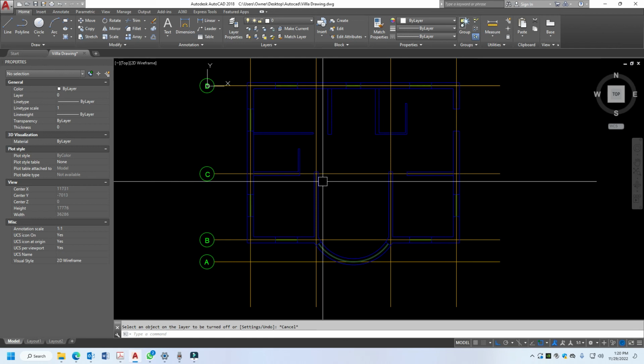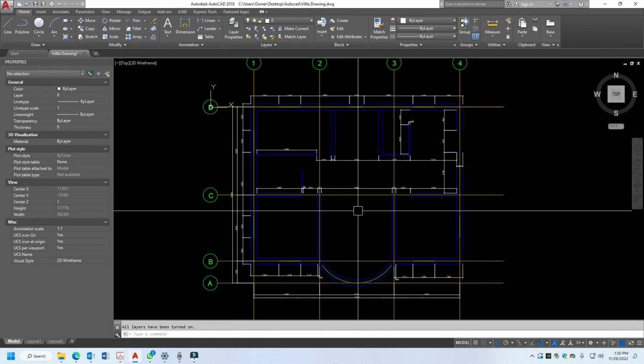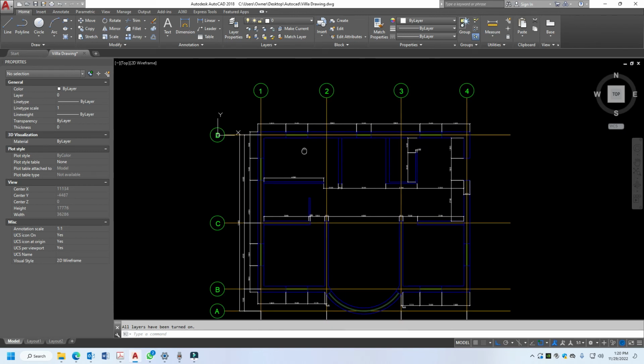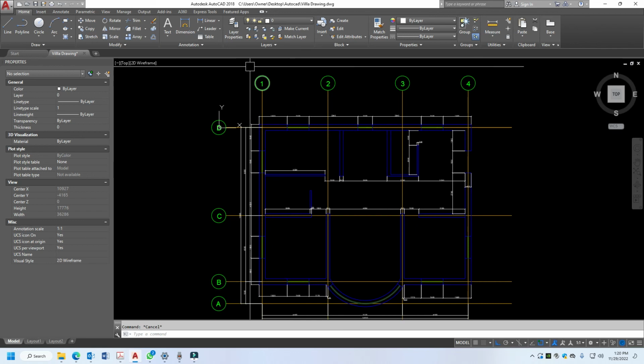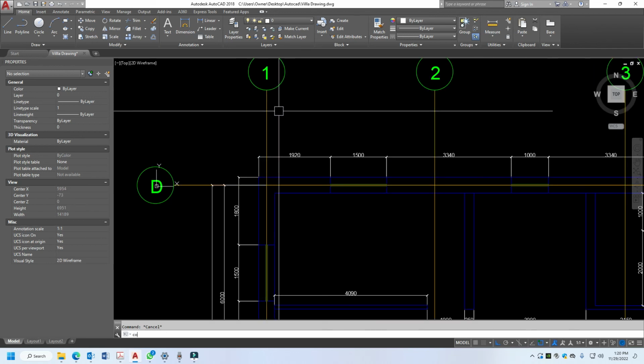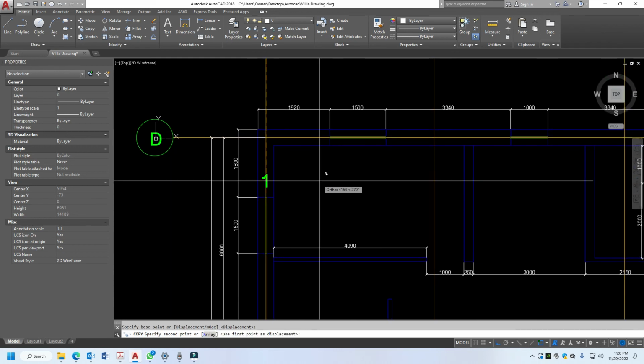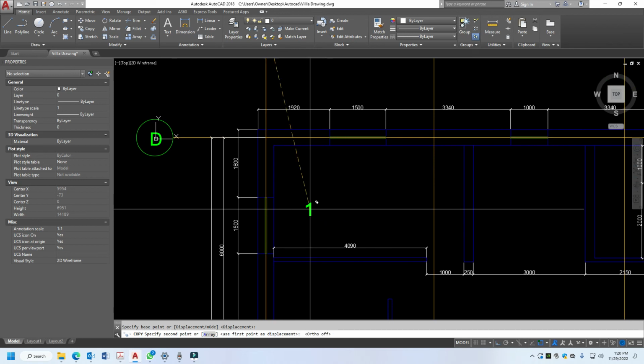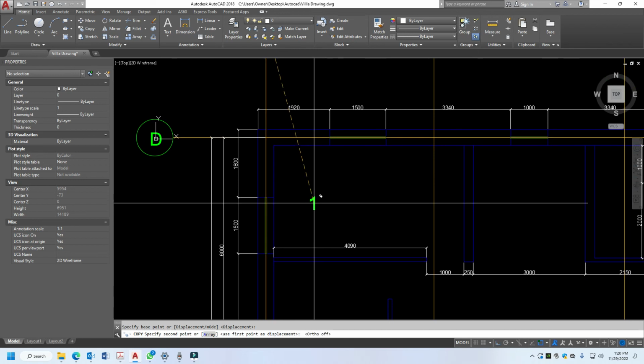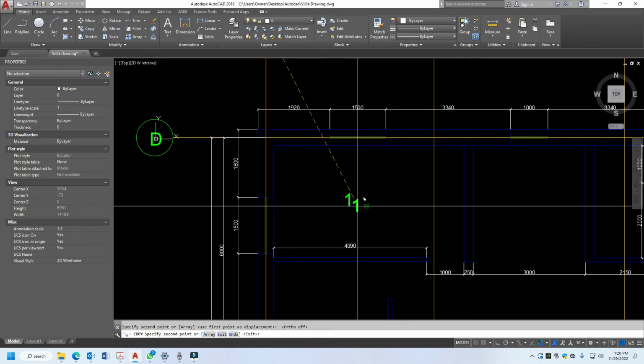Next thing you need to do is create a room text or room label. Just copy the grid one. Copy, space, click, space, then click. To keep it straight, turn on F8, then make it center, then double click, then type kitchen.